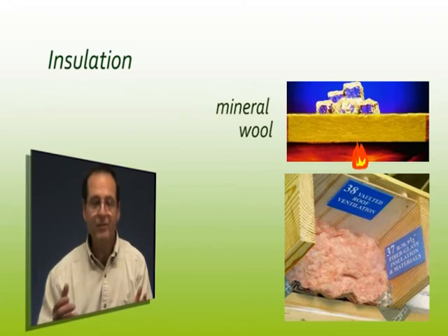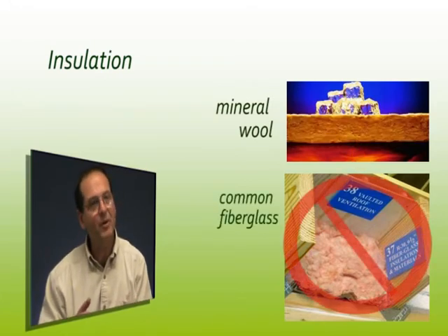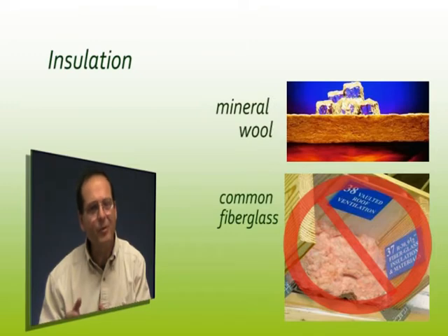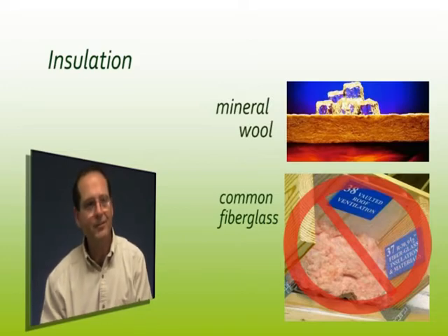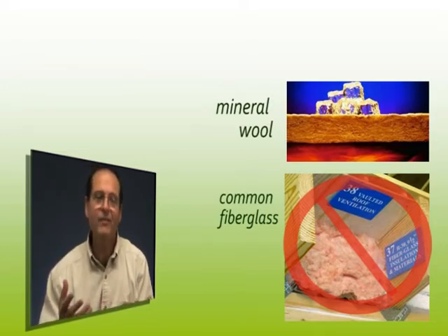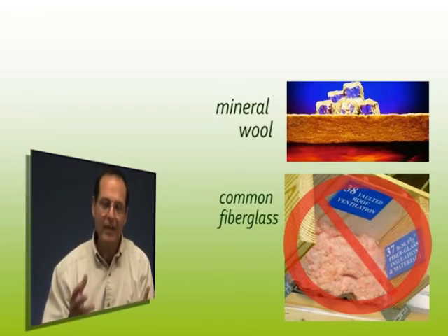In fact, fiberglass insulation doesn't do you much of anything. It doesn't help a whole bunch with sound, a little bit with airborne, almost nothing with impact, and it doesn't do you any good with respect to fire. Let's continue. So now we've got enough information and we know exactly what we're dealing with.